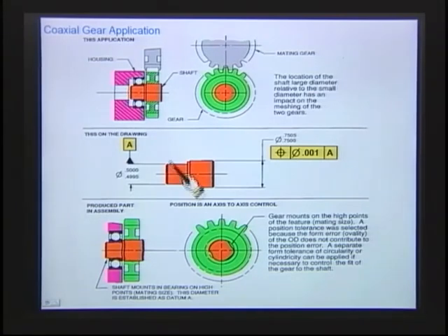So ovality, this little bearing here doesn't know anything about the ovality. Over here, the same thing. If I took that gear and pressed the gear on, you see what it does is it contacts on the high points. Ovality is not part of my problem here. What I'm looking for is axis to an axis. And if I'm looking for axis to axis, a position callout would be more appropriate. So I would use a position callout on this because I'm contacting on the high points.